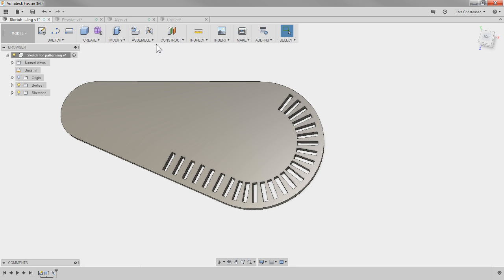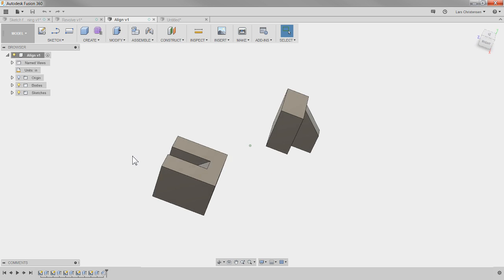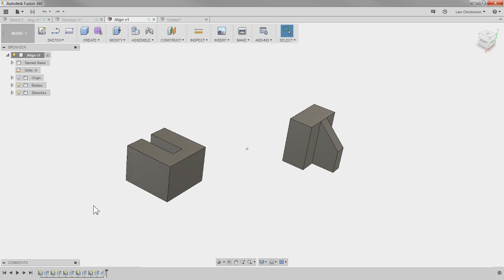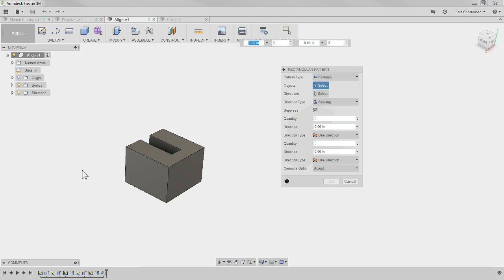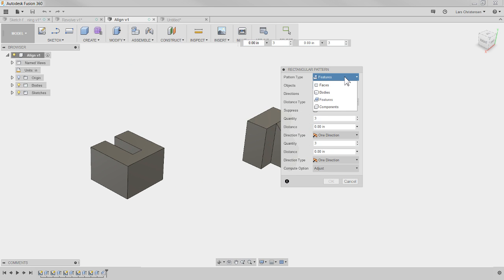I'm coming up on the end here, but I just wanted to show you. This is the example we used yesterday with the align and joint command, that you can also pattern bodies. So could be nice for people to know too, right? And components, by the way. So you can do that too.